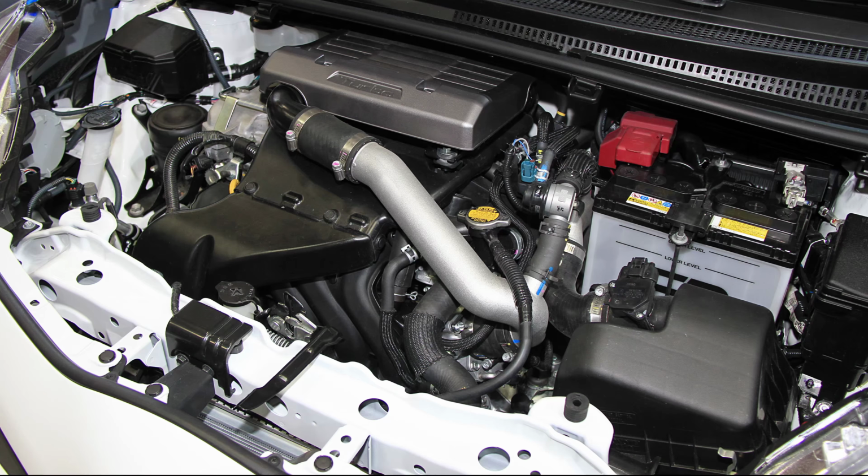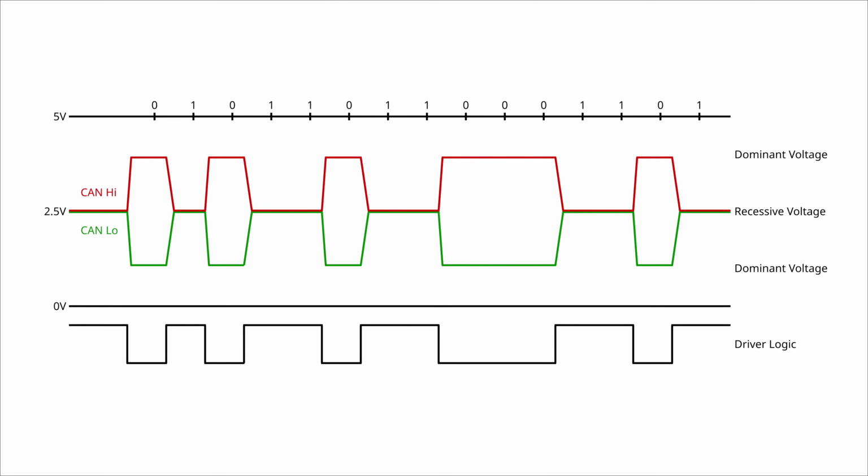Since CAN bus is utilized in high-noise environments like cars, when it was initially designed, it adopted the differential signal format method. It contains two lines. One is named CAN high, the other is CAN low. The waveforms of those two lines will be opposite to each other. The signal is between two lines. To observe the signal, simply subtract the two signals to obtain it.